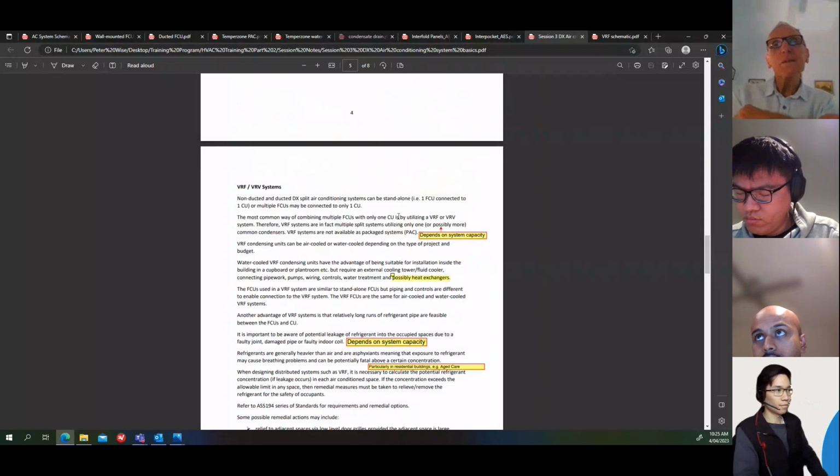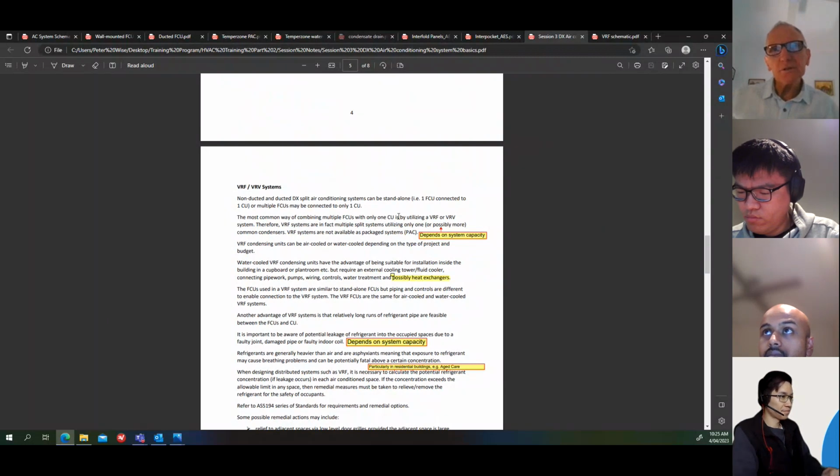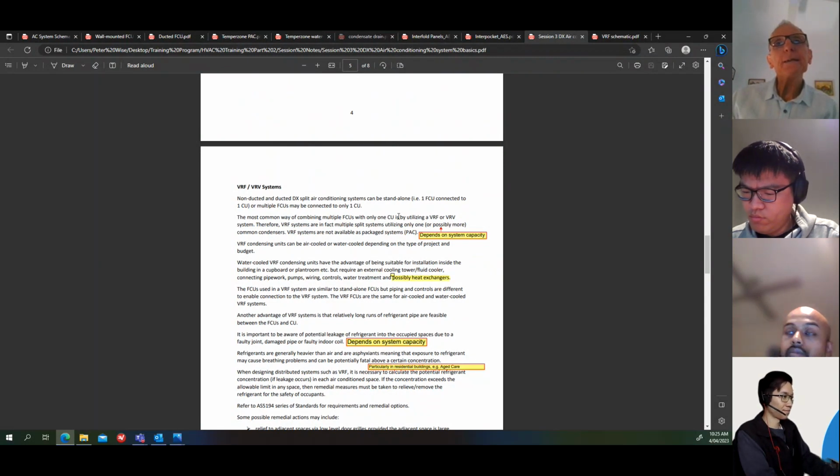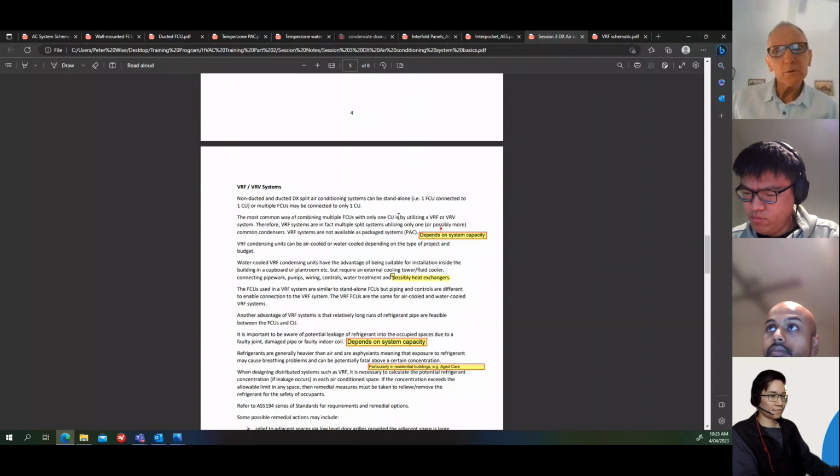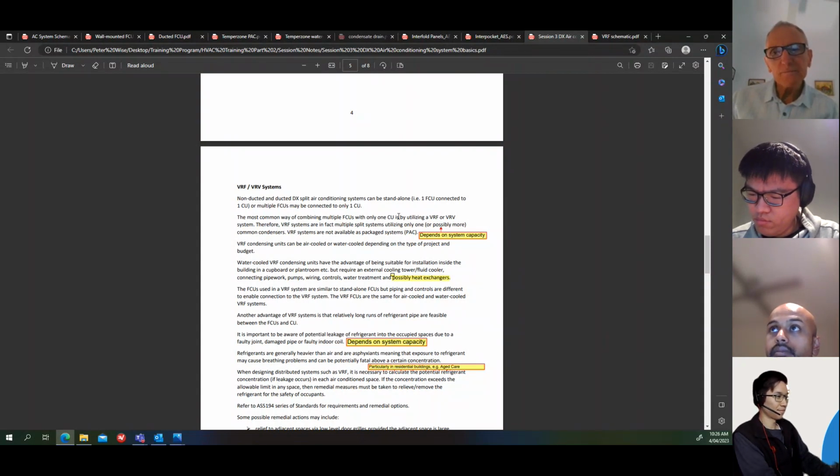There's another job that I was involved with, which was an apartment building, and every apartment obviously is an individual owner's property. It was about a 10-story building, and once again, this is an oldish building, so VRF wasn't available when it was built. So they decided the best way to go was to have a cooling tower on the roof and water-cooled package units in each apartment.